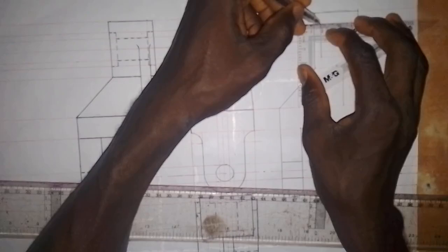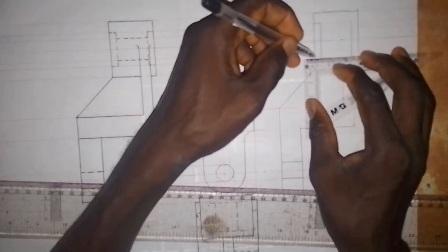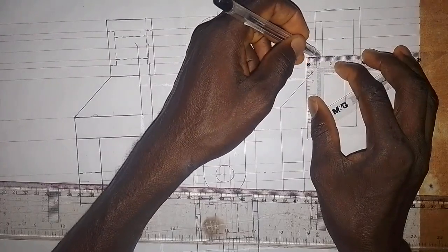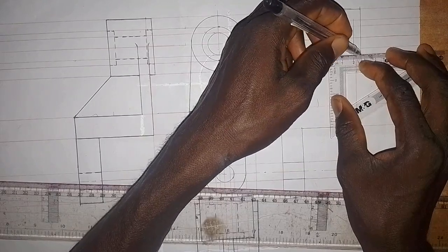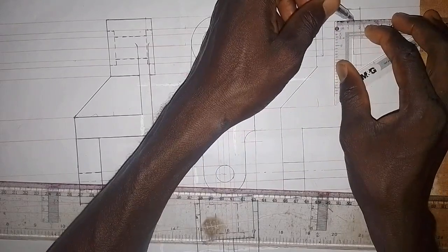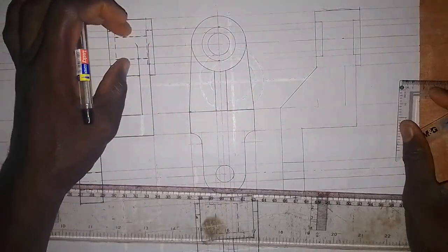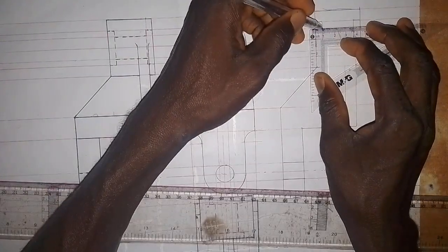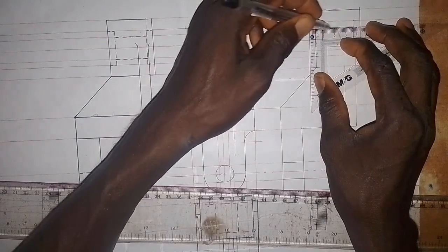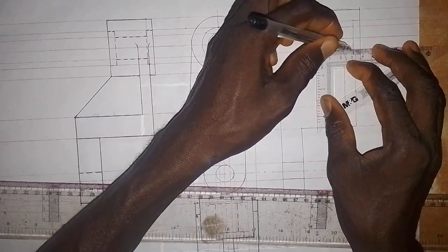Okay, so right now, this short distance, which is 6 millimeters, will be drawn as a thick continuous line. So we also do the same thing here from here to here. Okay, and then we also do the same thing from here to here. Now the hole that we now have inside, which is this one, will also be exposed, so we make this a thick line from here to this end. Okay, and then we also make this a thick line from here to this end.